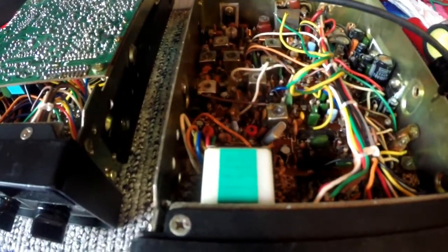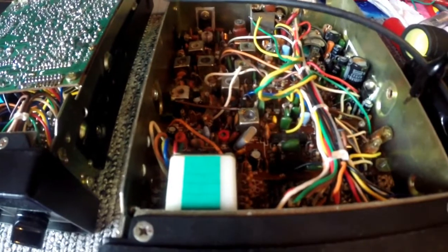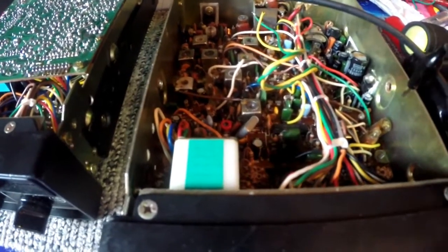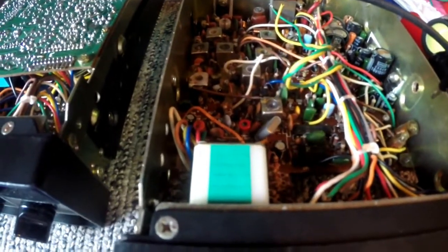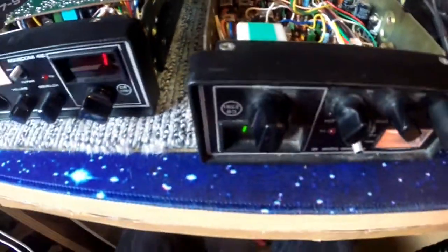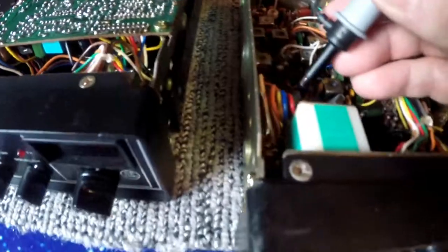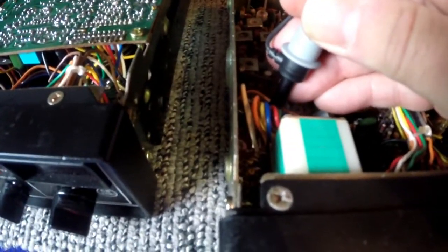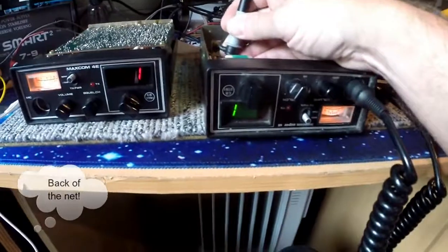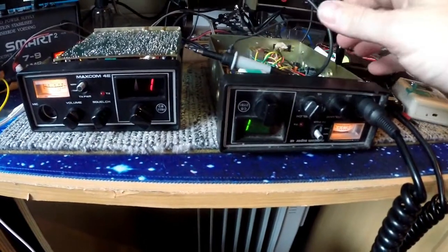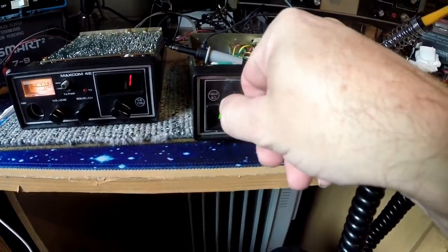The difference between the B that was in there and the C is the C has a higher gain, so it's okay to use it because I'm going for a better gain. I can't go to a worse one, so I couldn't have gone to an A. Now, if I now probe pin 19 of the PLL, 16.90593, so the 16 megahertz signal is now getting through to pin 19.